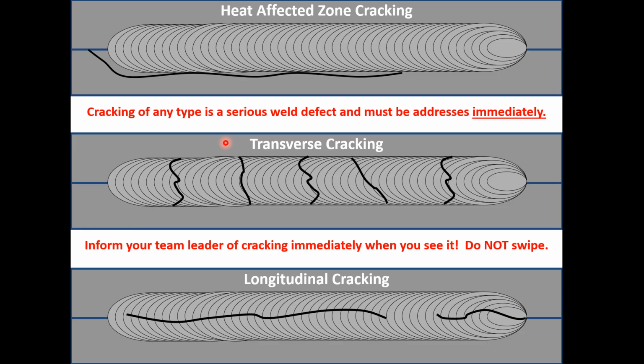And you see welds that look like this. Now, often these welds extend into the base metals. Often they do. If these cracks do extend into the base metal, that part would be junk. Because now, again, we've got to start putting weld out where weld is not supposed to be. So, I'll give you an example of transverse cracking. I'll give you an example of the condition where I've seen it in automotive.